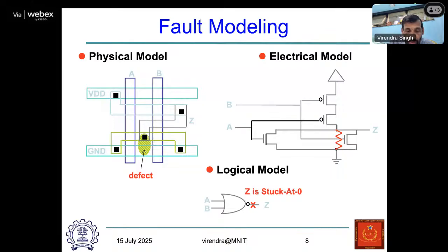And as I mentioned yesterday, about 60-70% of faults it can detect, and that's good enough for the industry. And hence the single stuck-at fault model survives till date. So everybody is using the stuck-at fault model at least. That means they have to generate the test for single stuck-at faults.